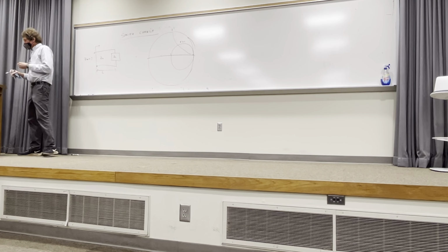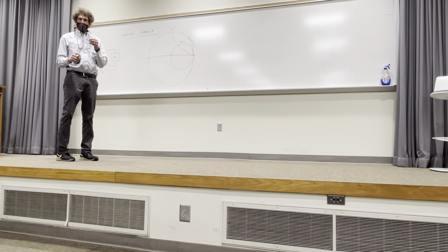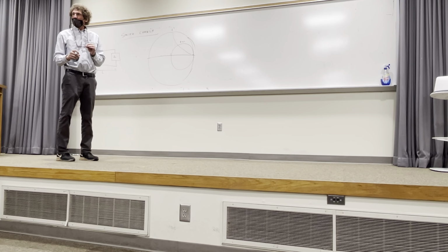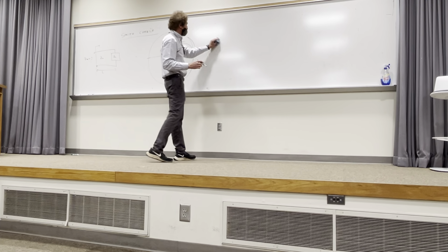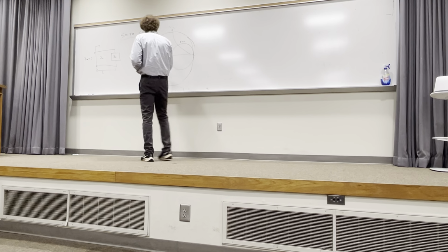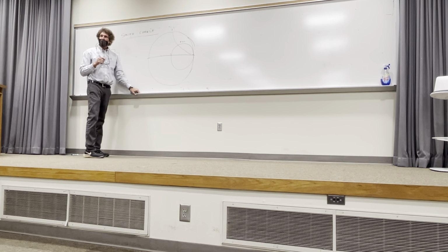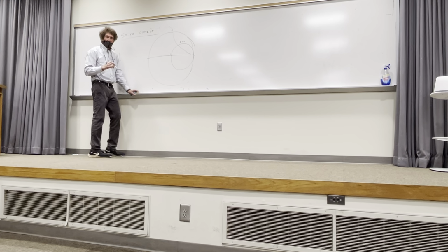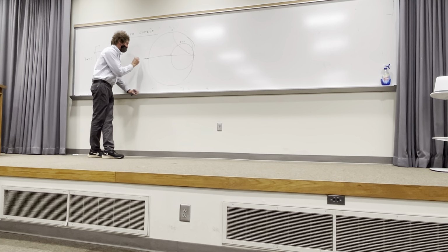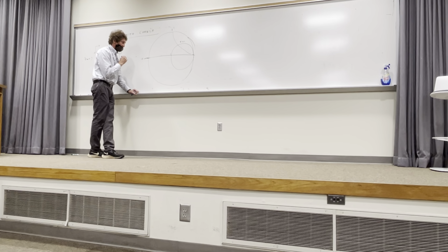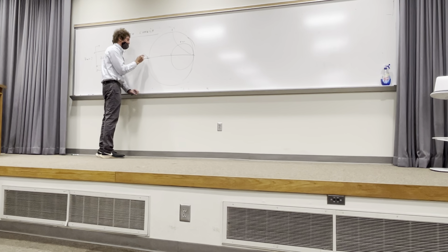Now we're going to take a look at how we get the input impedance. We mentioned how to get the standing wave ratio, VSWR. But this is going to be all done using normalization. Whenever you have a Smith chart, the very first thing you do, by the way, let me make a few comments about what I call the general properties of the Smith chart, or things that are on there you need to know. The first is this. At this point is the reference of 0. This is the mile marker 0. And it also has an impedance of 0 right there.